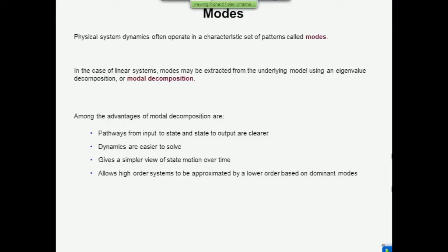and it makes it clear where the dynamics of the system are. Because by exposing where the eigenvalues are, you know which are the dominant modes and which are less important. Remember, the eigenvalues to the left in the complex plane are decaying more quickly than those to the right, those closer to the imaginary axis, if it's a continuous time system, and there are parallels to that if it's a discrete time system.